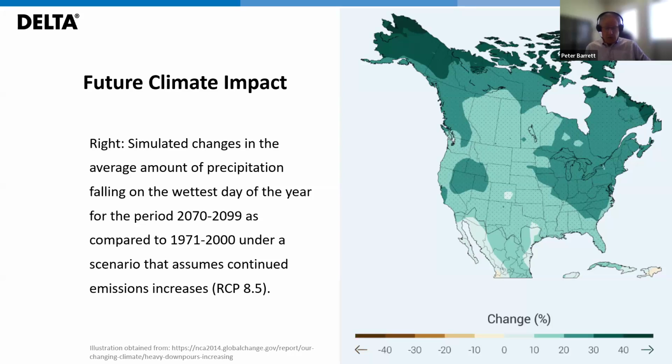Designers can select drain boards assuming 100% of the claimed flow rate on the technical data sheet, but under real world conditions, only achieve between 22 and 80% of the claimed flow rates. The gap between the assumed and the in-service flow rate can result in undersized drainage systems that are already less than increasingly extreme precipitation events require. This may result in damage to below-grade structures or roofs, more unexpected costs, inconvenience, and general pain in the butt to try to repair.